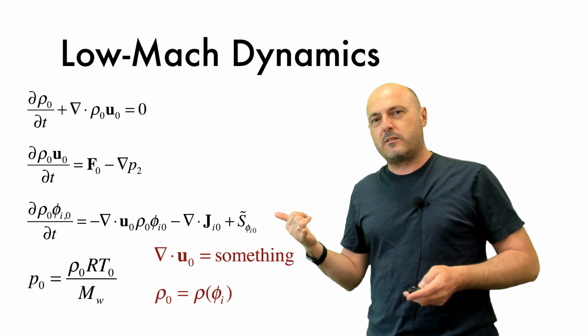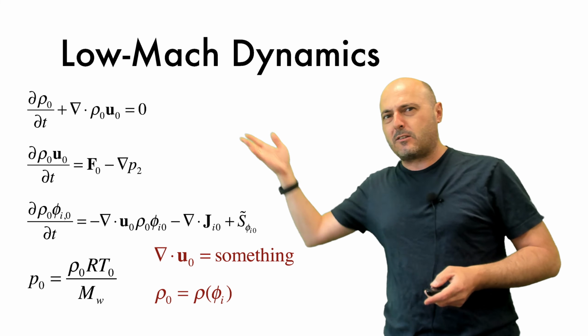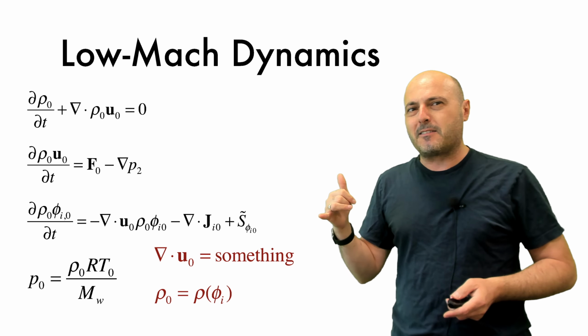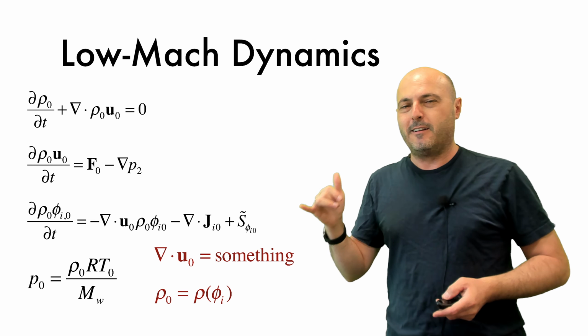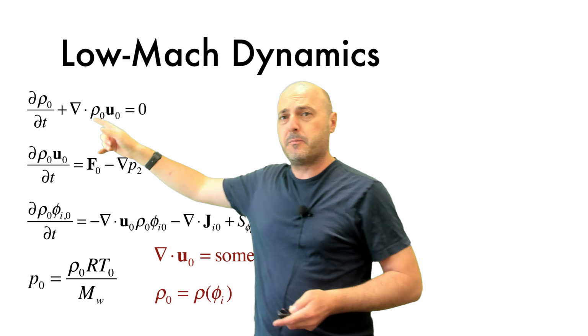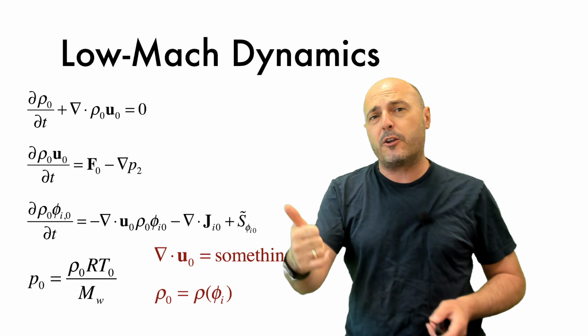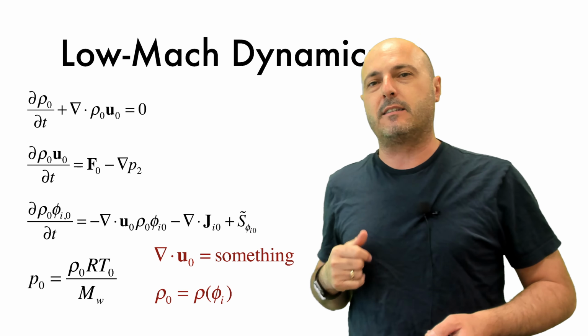Now, when you do this, look at that. You get almost the same equations. These are the low Mach equations. They look identical, but they're not, because they're only solving the non-acoustic portion of the equations. Now, for continuity, well, they're the same. I have a subscript 0 over here. This 0 indicates the non-acoustic portion of the density, okay?